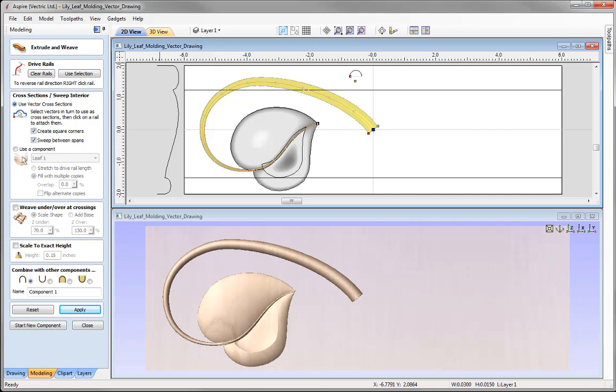And one other change that I'd like to add, and that's the actual thickness of the cross section for our stem. Now we can see, looking at the cross section that we already have, we've got the larger cross section coming in to the smaller cross section, which is this one here, and I feel that it's coming in too thin too quickly. So what I'd like to do is look at adding in another large cross section somewhere around here just to maintain the thickness of the stem.